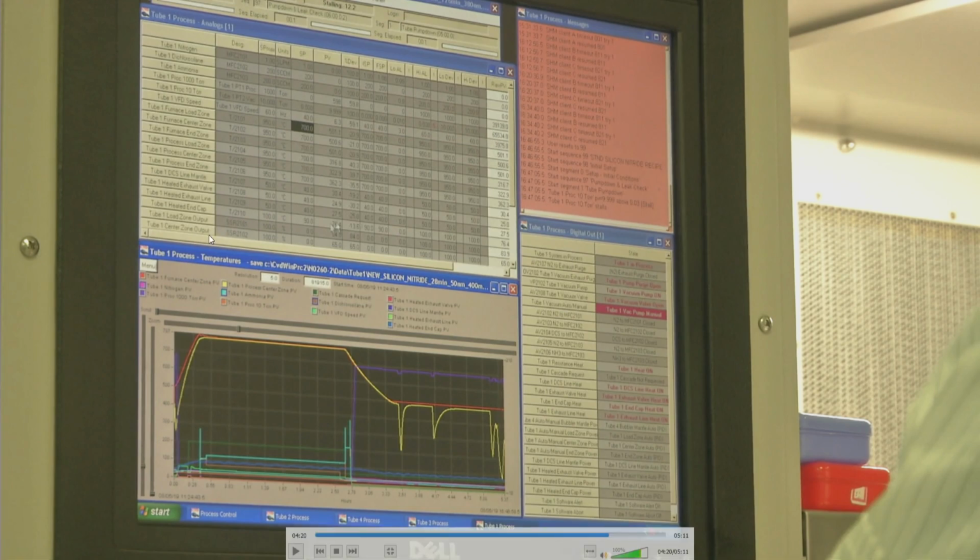And not just that, we also have to look at what the flow ratios or the pressures should be. All those things are controlled through this program. You can see here the pressure control. We have to put in the right pressure that we need, and also the MFCs, the mass flow controllers for various gases, right? So the mass flow controller for dichlorosilane here, ammonia, and nitrogen. All these flows are also controlled through this program, right?